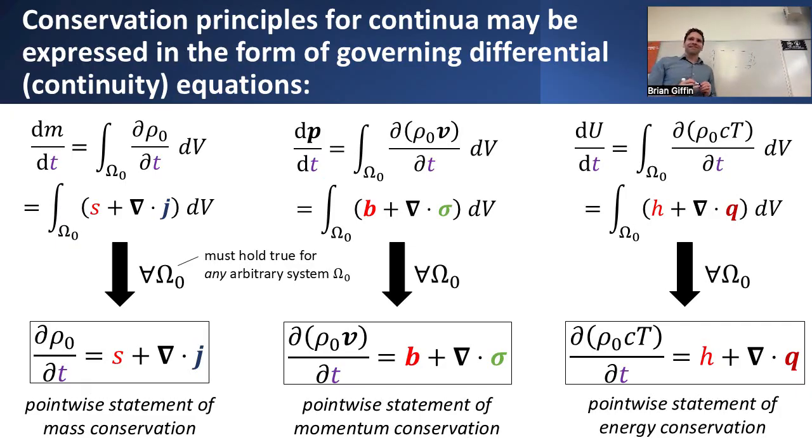And I can say that the net momentum change of this cantilever beam basically has to be balanced by whatever external forces are applied to this system, maybe also including reaction forces or things acting on the boundary, and maybe any body forces acting over the interior volume. That has to hold for this particular choice of my system.